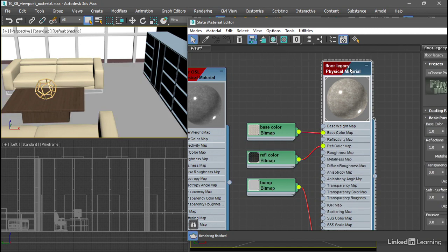And turn it back on again for the material. And you see once I selected that, the button turned itself off again. So now I'll turn it back on. All right, so for a basic or legacy material, then the Show Shaded Material in Viewport option will be fine.